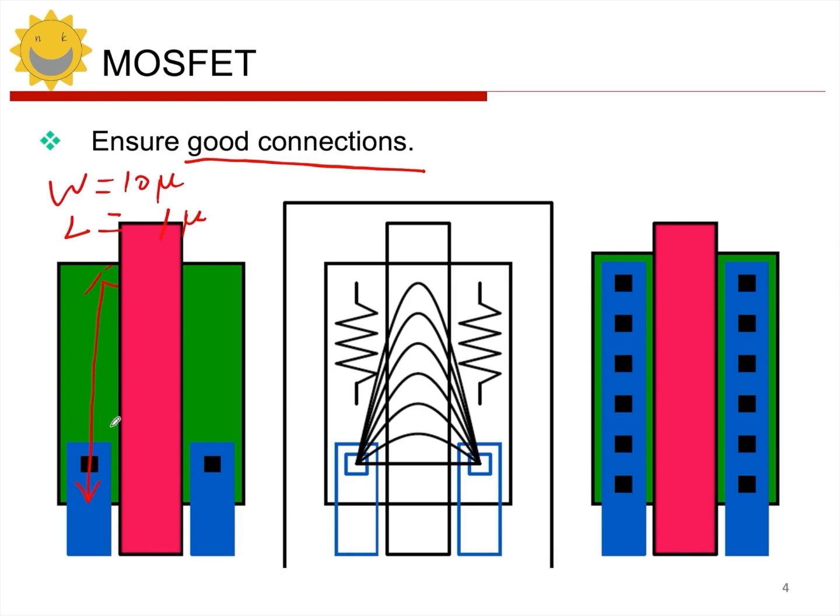To connect the source drain region, I definitely need to use a contact to connect it to M1. I'll put a contact near the bottom and then connect it with metal. If I make a connection like this, the DRC check is fine.